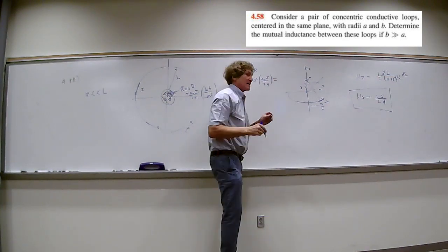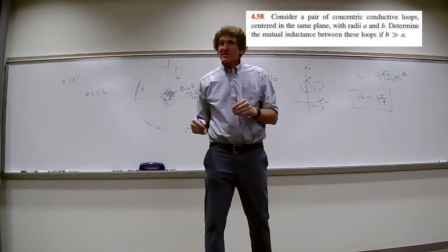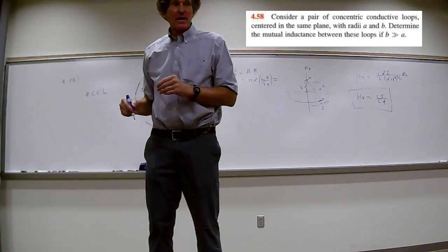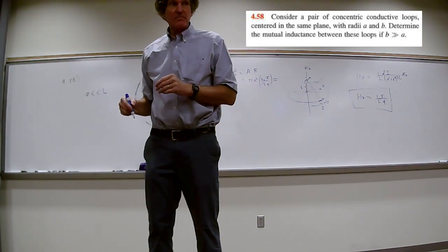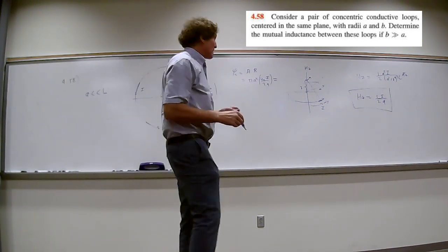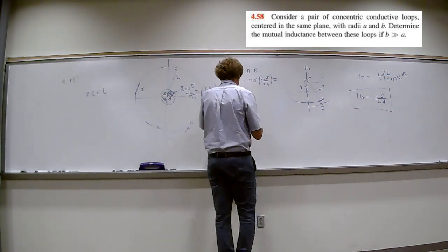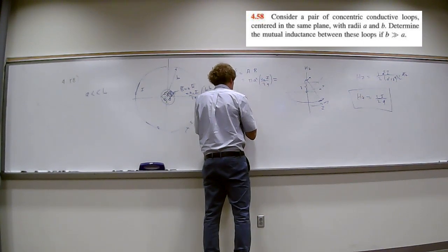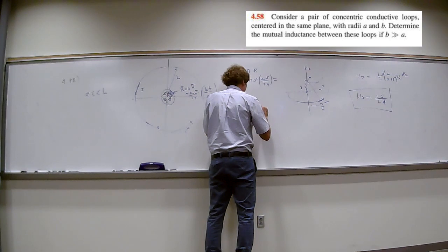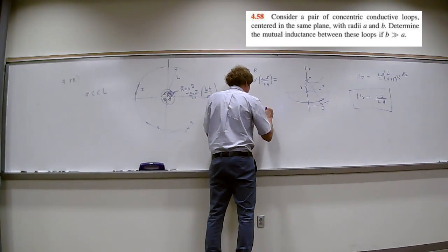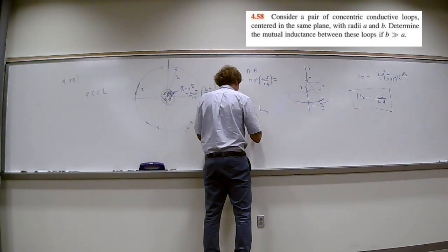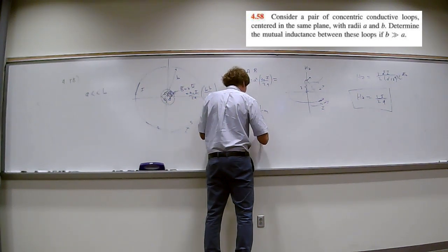Now that's the magnetic flux. What is magnetic flux in terms of inductance? I times the mutual inductance is the magnetic flux, isn't it, class? So if you take the magnetic flux and set it equal to I times, I'll call it Lm, it's mutual, you can see that the mutual inductance is simply the magnetic flux divided by the current.